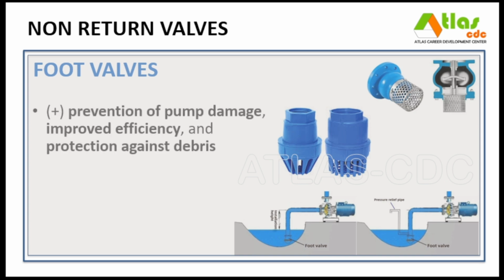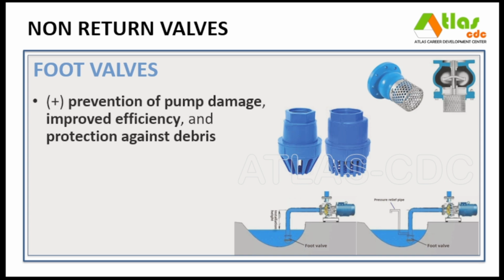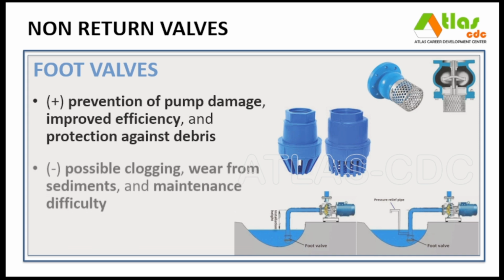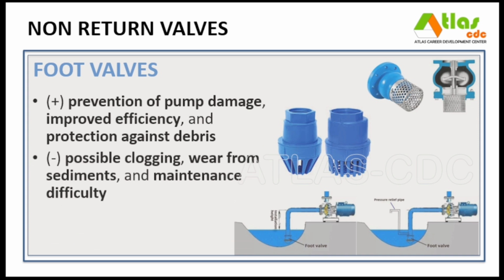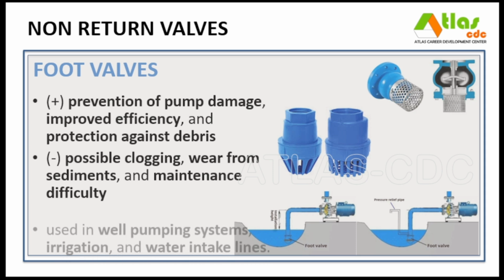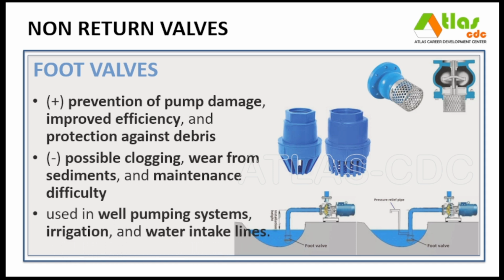Its advantages are prevention of pump damage, improved efficiency, and protection against debris when equipped with a screen. The disadvantages include possible clogging, wear from sediments, and maintenance difficulty if submerged. It is typically used in well pumping systems, irrigation, and water intake lines.